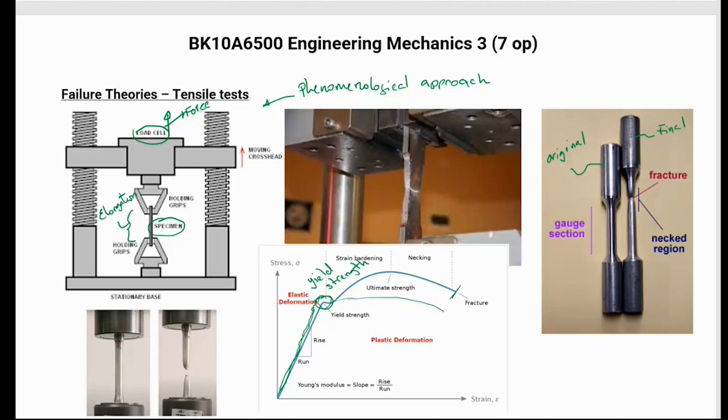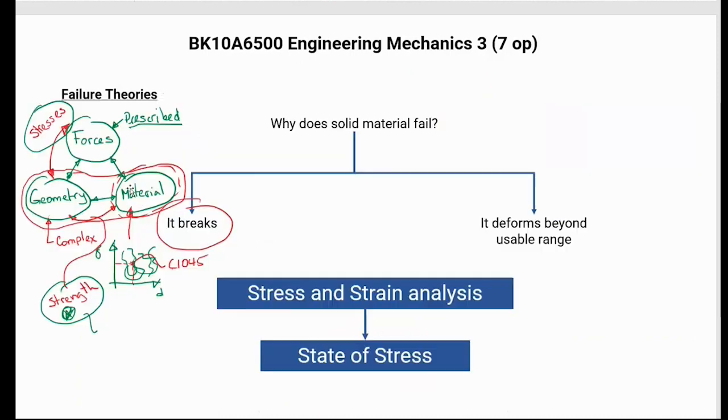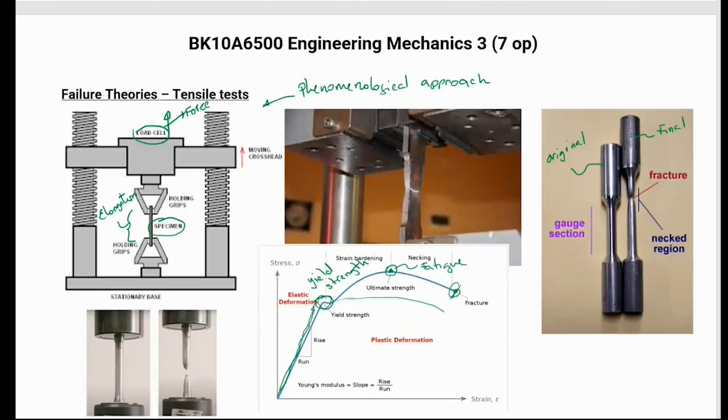Another important part is this one, or this one: this is the ultimate strength, and then this is the fracture strength. Something like this is used for fatigue at some point, or both are used for fatigue. And yield strength in certain theories. The question now that we need to ask ourselves as engineers is, which value do I use to determine if these stresses are larger than the strength, or whether there is no breakage going to happen there? Before I jump into the other slide, because we're going to deviate a little bit from this, what questions do you have?